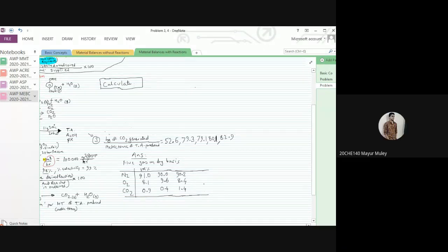Nishant? Sir, I'm getting 65.3 kg. 65.3. Nishant, your volume percent of flue gas, dry basis? Sir, 90.88. So we'll just say 90.9. Just round off and tell me. 7.6. 7.6. 1.4. 1.4. They don't add up to 100. They do, 99.9. So kg of CO2 generated is 82.7.